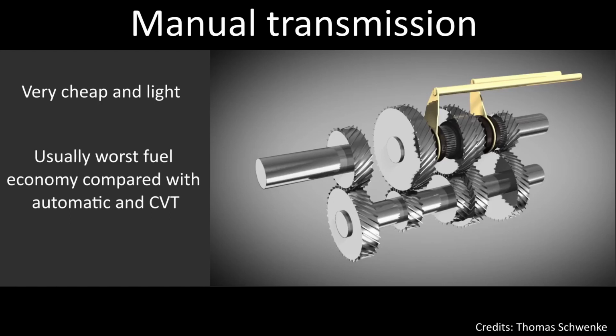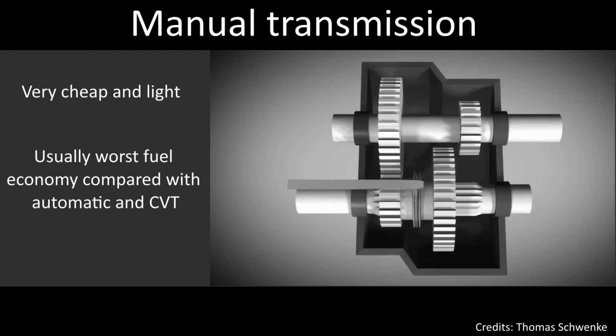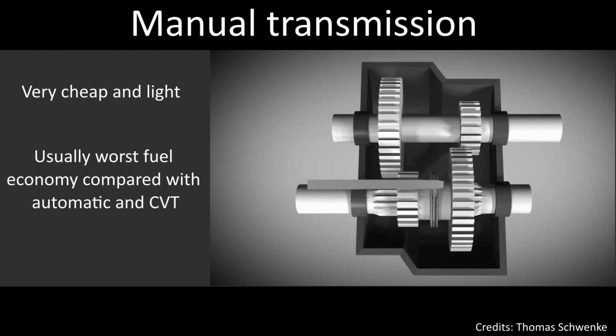It uses a driver-operated clutch, usually engaged and disengaged by a foot pedal, for regulating power and torque transfer. Meanwhile, the gear can be chosen through a gear selector, operated by hand. So the difference from an automatic transmission is that the driver has to operate the gear stick and clutch in order to change gears. Now, let's try to understand how it works when our car is moving, with this simple animation, where you can see the gear selector in action.